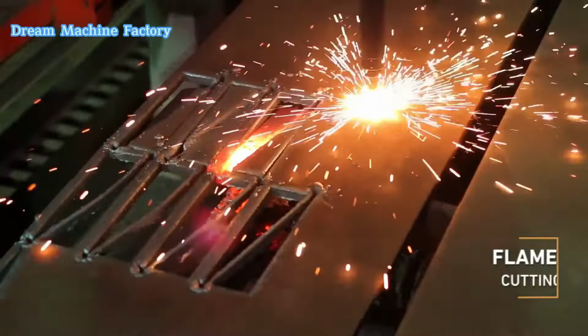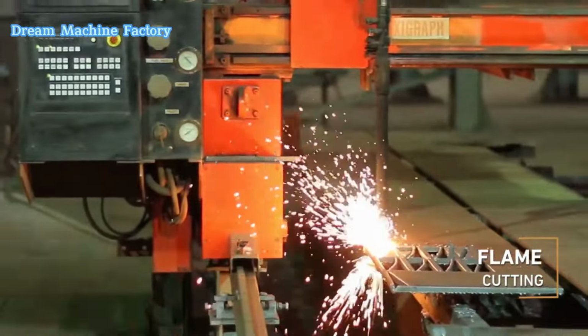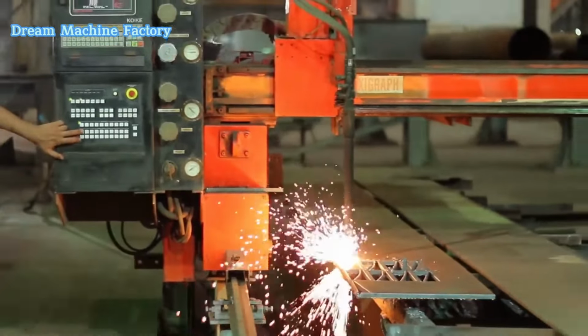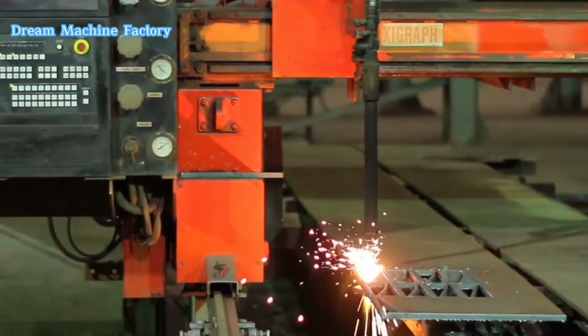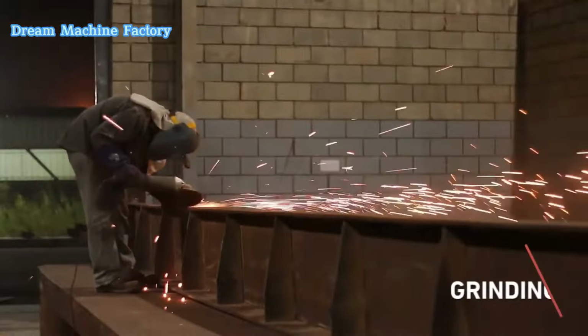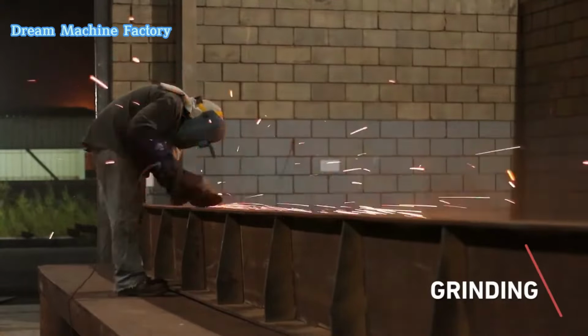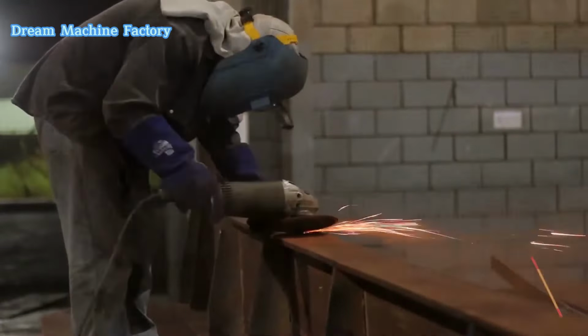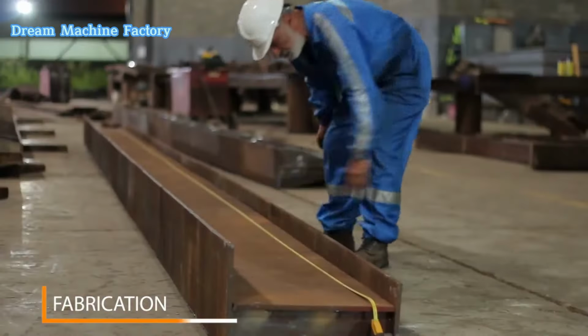Once the design is finalized, the steel plates or sheets are cut into the required shapes using flame cutting. Oxy-fuel cutting, plasma cutting, or laser cutting methods are employed to achieve precise cuts. After cutting, the steel pieces often have rough edges and irregular surfaces. Grinding smooths out these imperfections, ensuring that the pieces fit perfectly during assembly.